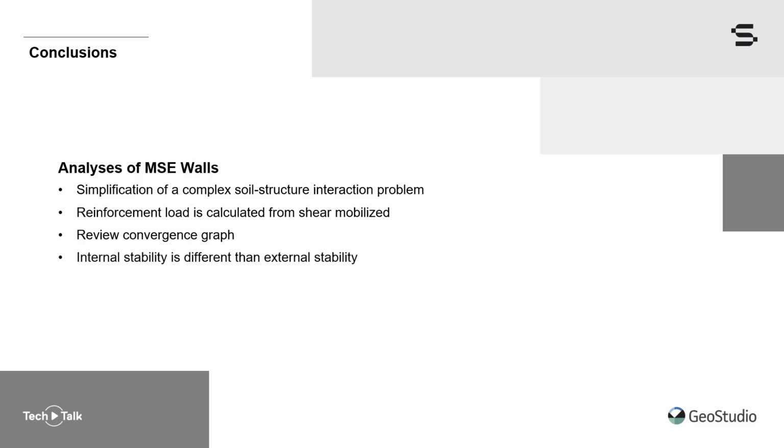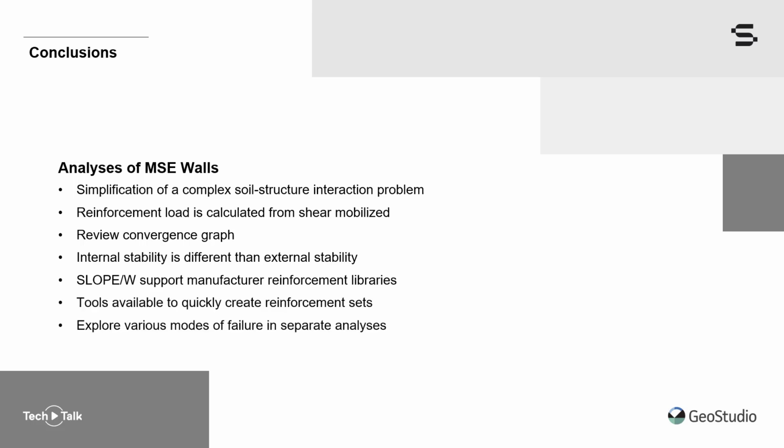Keep in mind that SLOPE/W should ultimately be used to address the overall stability of the retained system and not to analyze internal stability, which approximates the load in each individual layer of geosynthetic and compares this value to the tensile capacity. Finally, SLOPE/W provides a number of features to support the workflow for analyzing MSE walls, including manufacturer libraries for geosynthetics, a number of user interface tools to create multiple reinforcement, and the ability to explore different modes of failure using the cloning feature within the analysis tree.